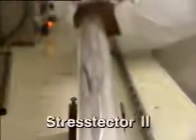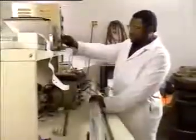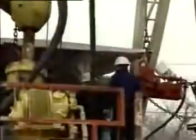A new version of the Homeco Stress Tector, the Stress Tector 2, is being introduced for slim hole, coiled tubing, and high temperature situations. The smallest size Stress Tector 2, at 5/8 inch diameter, has been developed to handle pressures up to 20,000 psi and over 400 degrees Fahrenheit. Regardless of which detector is used, once the actual free point is determined, the free pipe can be removed from the wellbore after backing off from the stuck section of pipe below it.